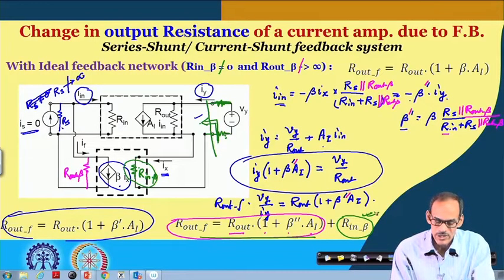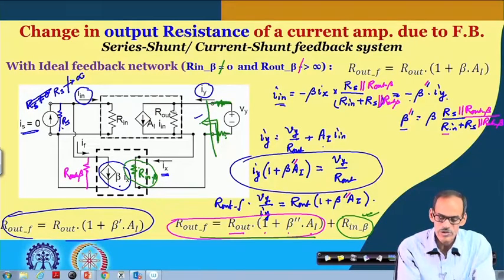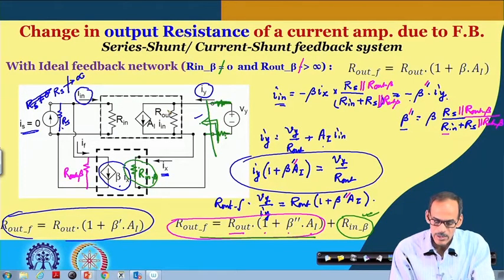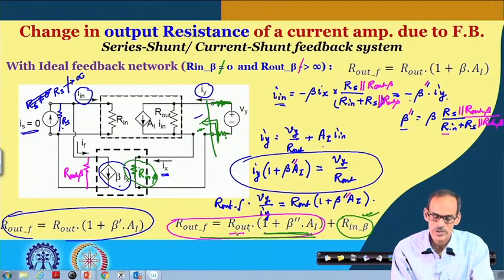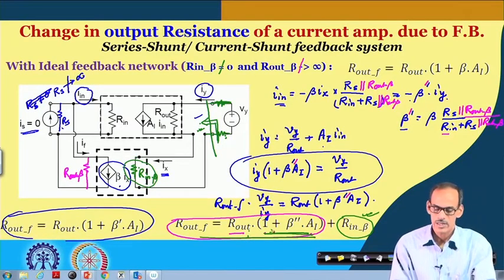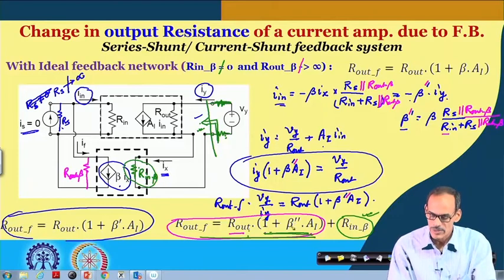And also we have seen that the output resistance gets increased because of this series connection here, and the increase is essentially this desensitization factor helping us to increase the output resistance, or we can say the output conductance gets reduced by this factor. And we need to be very careful while we are considering this load affected beta.